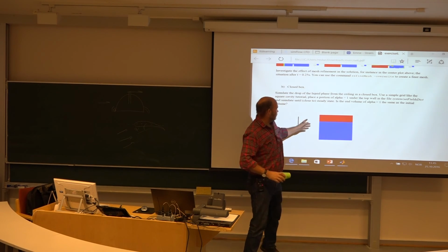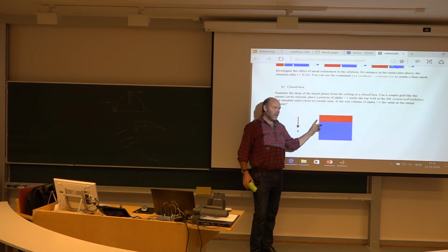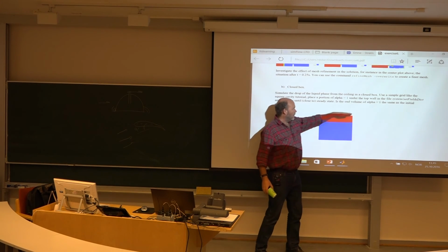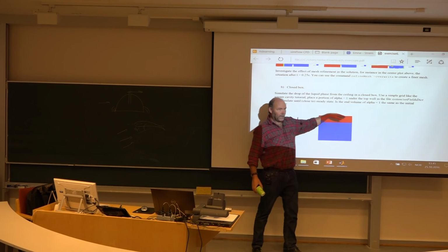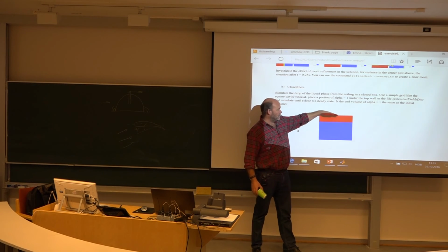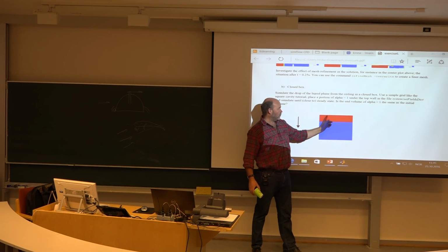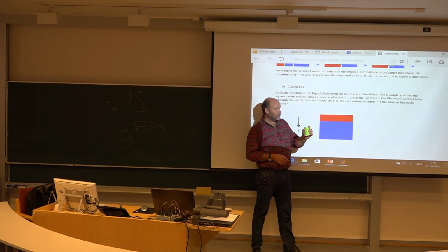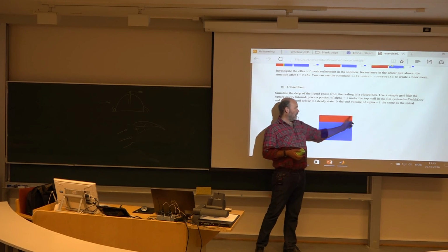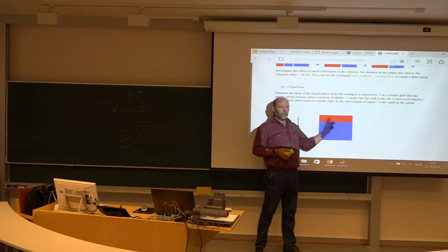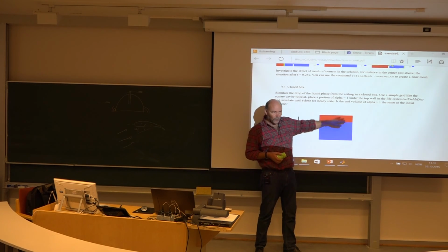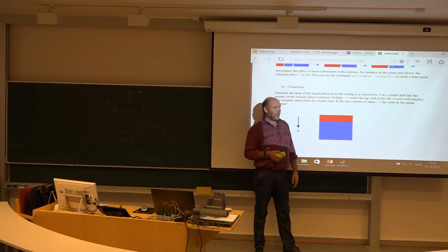Same will happen here. Initially, when you try this simulation, and if you have not an atmospheric opening, but it's a solid wall up here, it will have trouble starting to fall, because there will be a vacuum behind it, so it won't fall. Of course, it will, at least if you have some 20, 30, 40 cells here. It will eventually start to fall, but it will take some time. Just have a look at it.